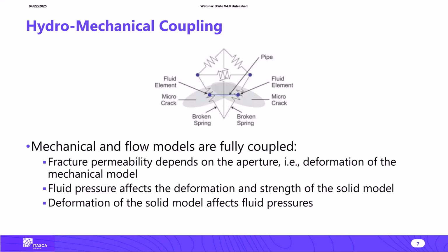The crack in the flow model acts as a reservoir, and we keep track of the pressure for each of these reservoirs. The microcracks, which are within certain distance, are connected by pipes, which then allow for pressure dissipation and a flow through the network of the fracture.